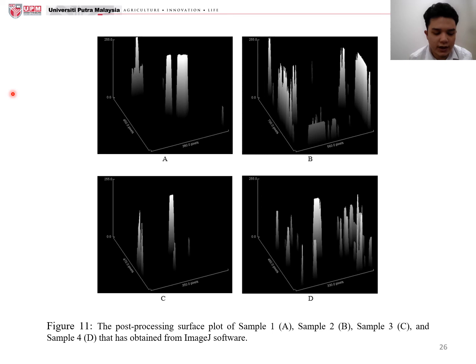By using sample A as an example, the contour plot shows a higher z-axis pixel value in the sample midsection where there is a defect for sample A. So to put it another way, after image processing, a larger pixel value on the z-axis may show damage to the sample. So no matter how much noise was removed, the processed image still had an inconsistent contour plot.